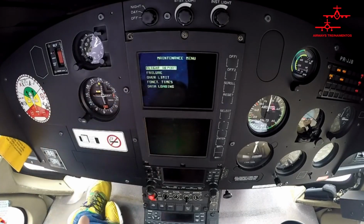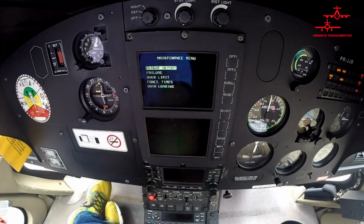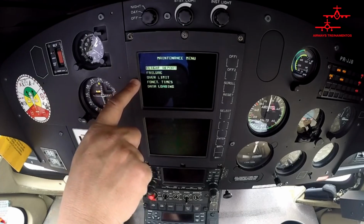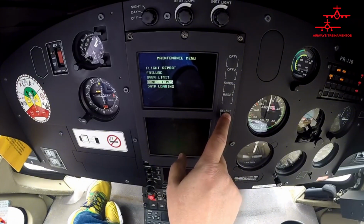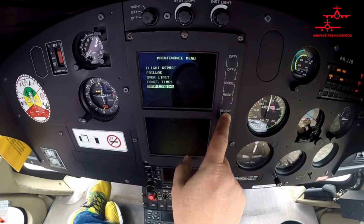There's the fly report, which I use when I want to see the latest fly reports from recent flights. I can check the faults that were recorded by the VMD, if there was any overlimit, right? Let's select here to see if there was any overlimit, accessing it here. This here shows how long it lasted. Is the VMD working? The operating time on this aircraft can be accumulated if it came from another aircraft. That's more. I think the manufacturer has an idea about that. And the data load is used when we need to load something, which is something the operator usually doesn't do.